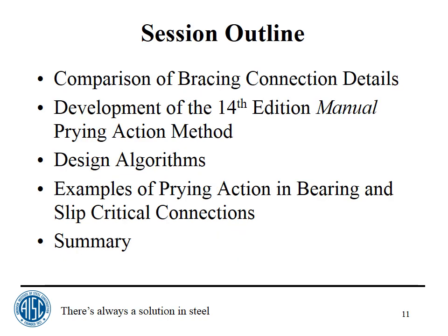This is an outline of what we'll cover tonight: comparison of bracing connection details, and then that will lead into the development of the 14th edition manual prying action method. There are two design algorithms, one's design, one's analysis for prying action, and then we'll go through an example of prying action for a bearing type connection and for a slip critical connection, and then we'll have a summary if time allows.